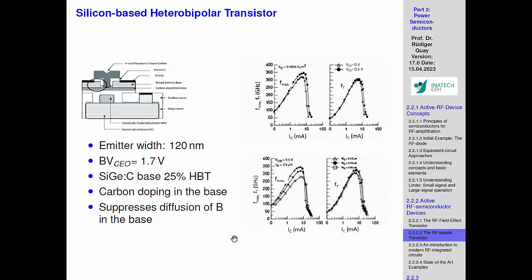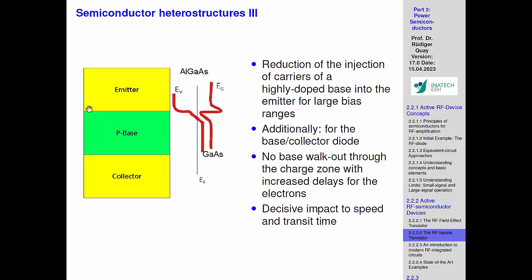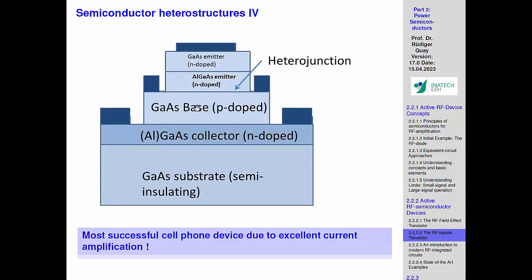And there's of course all the chemistry. For example, why is it so critical to put high doping concentrations in a base? We didn't talk about this, but if you put too much of something, that just diffuses also physically. And it's not just the electrons diffusing or the holes, you simply cannot put one layer with high concentration and then the next layer nothing.